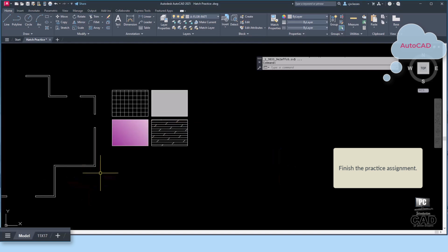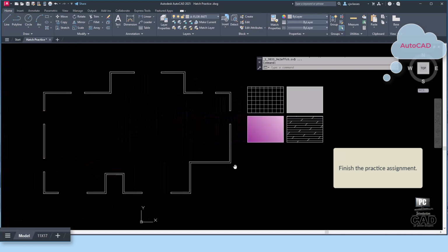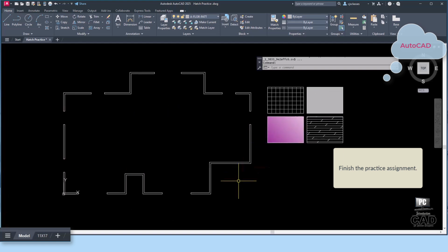The first critical aspect of this example that requires attention are the openings between the wall lines, where doors and windows would be located. The hatch command creates a repeatable pattern only when there is a closed boundary. Any open spaces will create an error using Hatch.